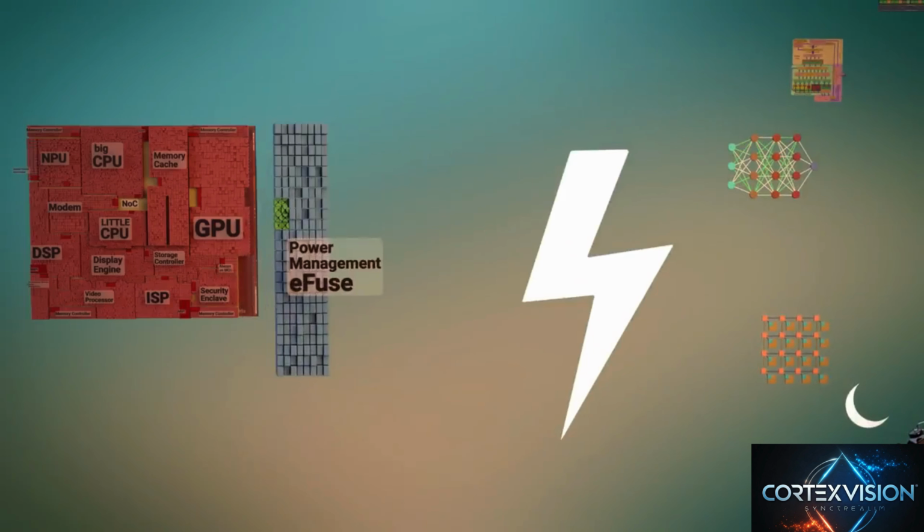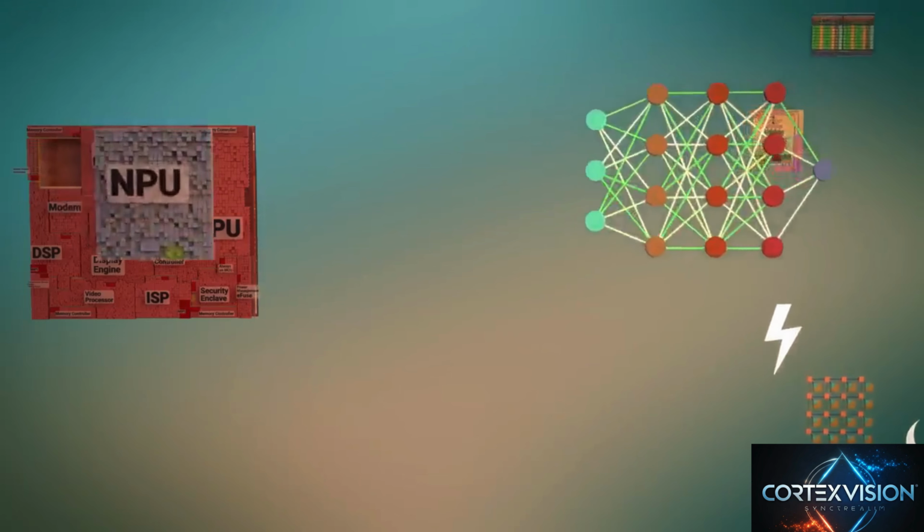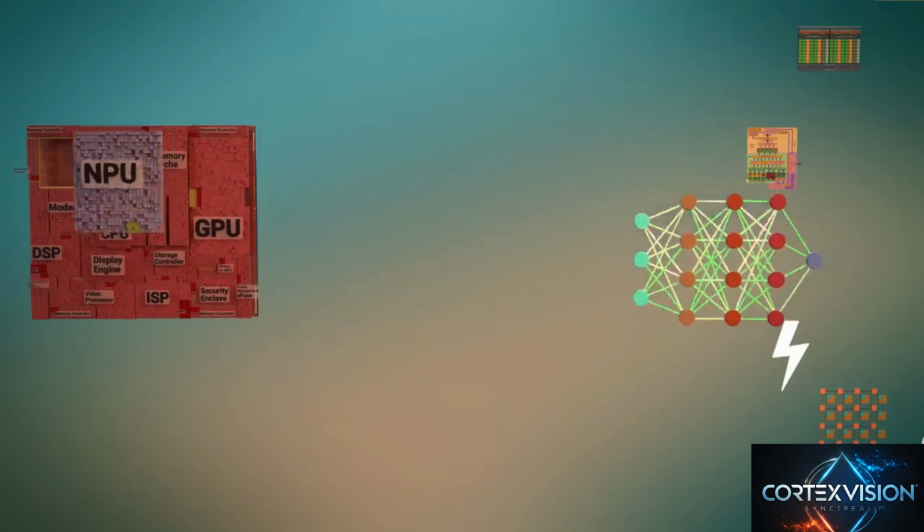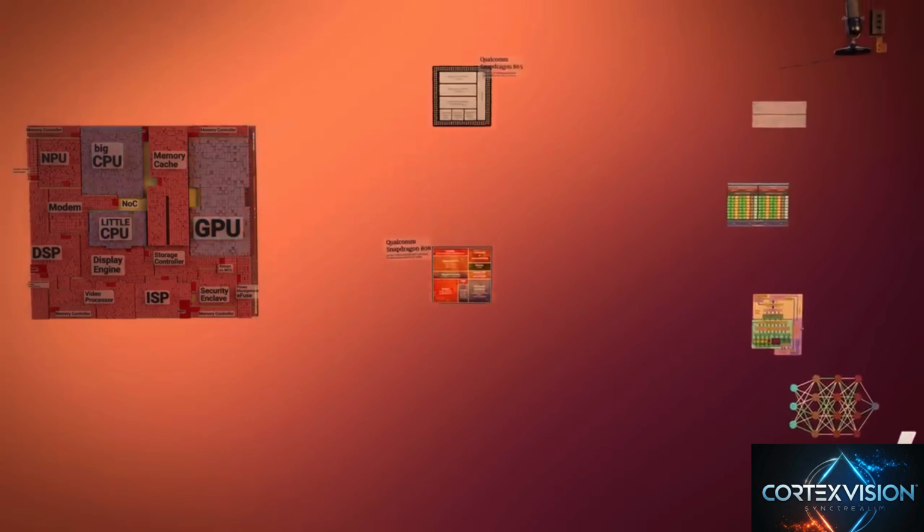Furthermore, some SoCs may have on board power management circuits that complement the power management performed by separate chips outside the SoC. Additionally, some SoCs, such as Apple's, have a neural processing unit, or an NPU, that is specialized circuitry that can execute machine learning algorithms far more efficiently than the CPU, both in terms of speed and, more importantly, power consumption.